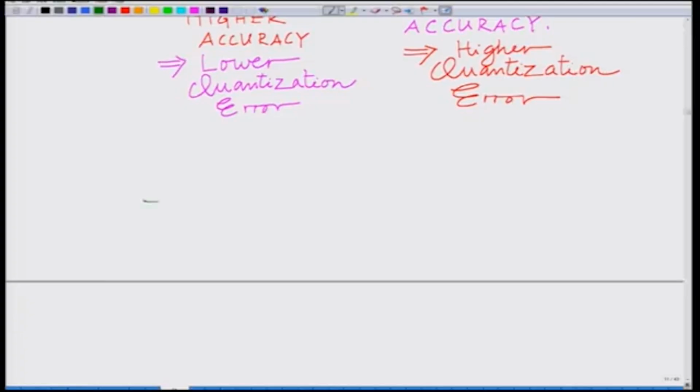So again, let us look at the dynamic range of the signal. If we place the quantization levels, we can have smaller quantization intervals, and progressively as the sample value increases, towards larger amplitudes these can be larger.